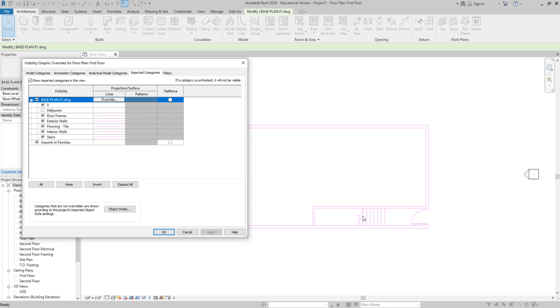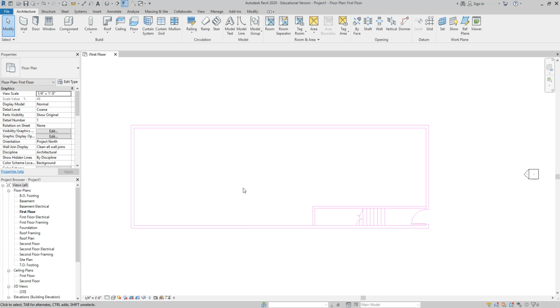So in my experience, whether you're working in CAD and X references, or whether you're working in Revit, it just makes it so much easier to have it be a color you'd never see. That way, I think it'll prevent you from accidentally printing it. So I always like to do that with my plans to begin with.